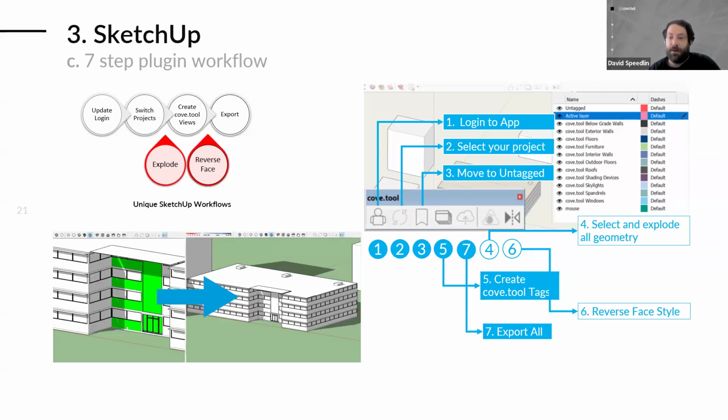The file should only contain the main building's geometry. Rendering elements, structural elements, and site elements are not typically needed for analysis. So it's best to hide those or get rid of them altogether, so that you can get results more quickly, and you reduce the amount of inaccuracies. If you have building context you'd like to see imported for daylight analysis, then that may also be included.